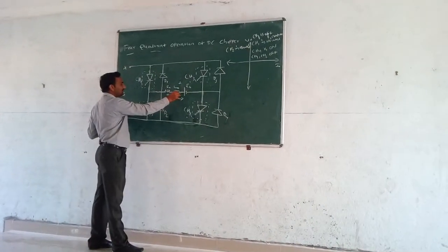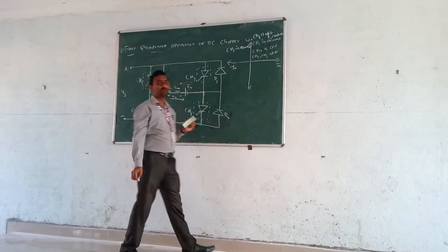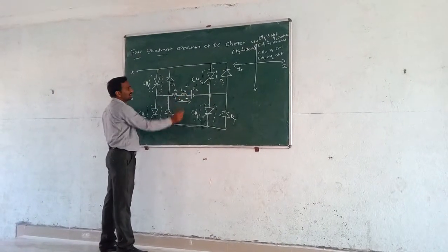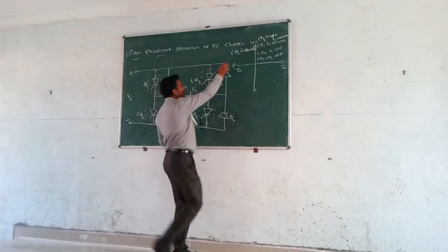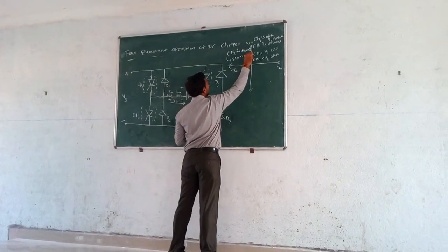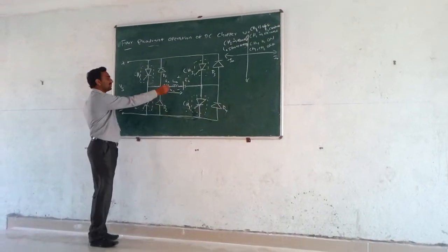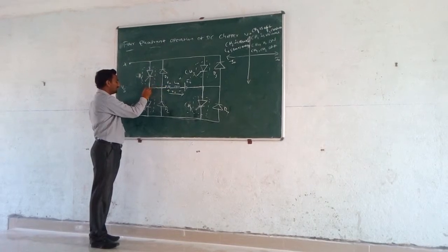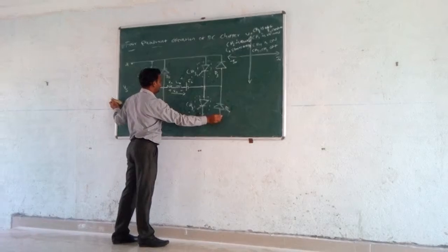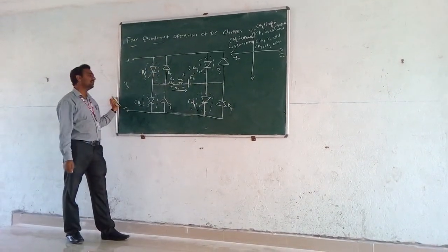In the second quadrant, the current is negative and the voltage is positive. At that time LA stores energy, and the current flows from the stored energy through LA, RA and CH2, through D4, and returns back to LA. This is the current path.